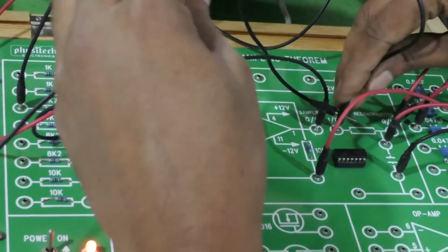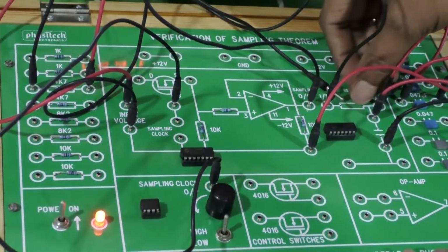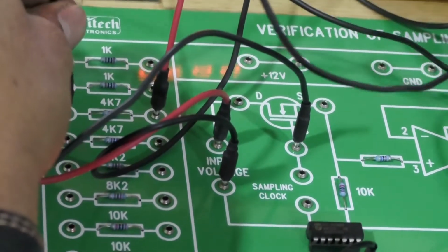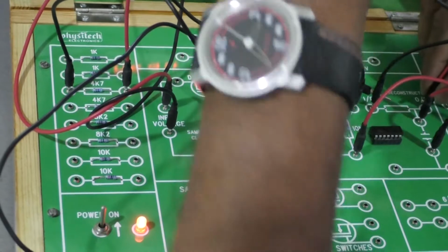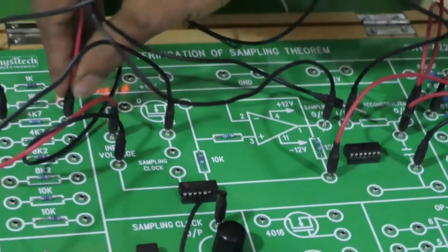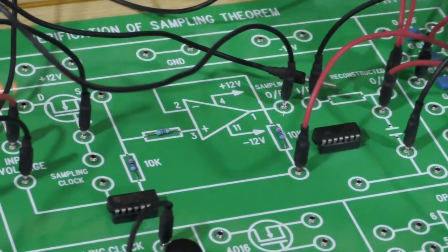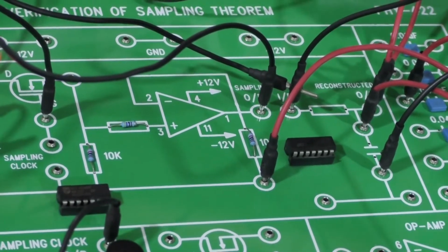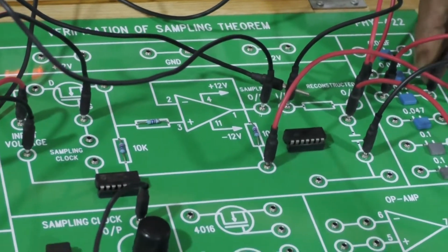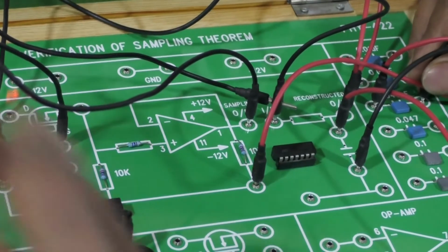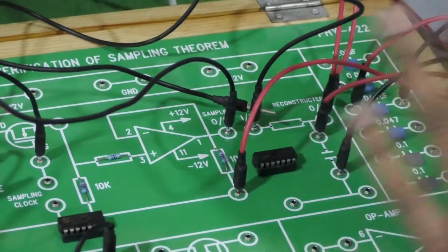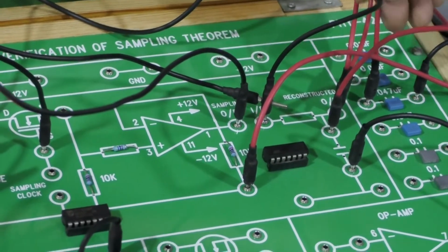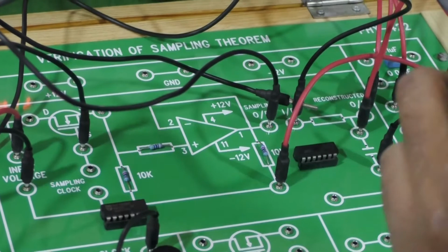Okay. The sampled input is given to the reconstruction circuit, and here we have one resistor. So here we have to connect the 4K resistor. One end is connected to the positive and the other end is connected to the second end. Here I am connecting the 4K resistor, and for the reconstruction of the original signal, the low pass filter frequency response is very, very important. If you want to get the distortionless message signal, you can connect the resistor value as 4K and the capacitor value here, this is the capacitor. So the capacitor value is 0.047 microfarads. Here one of the knobs is connected here and the other knob is connected here.